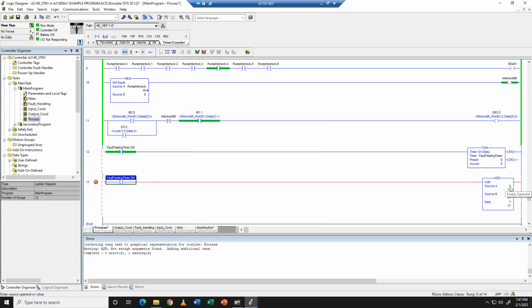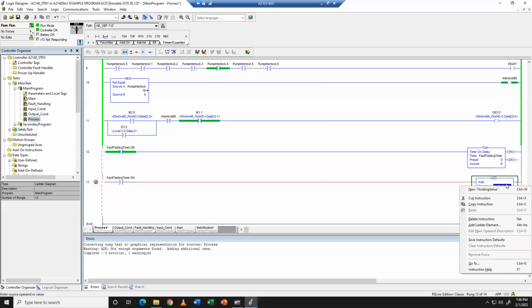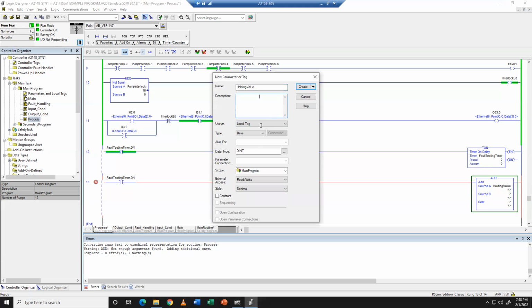So Wonderware, for example, I believe the character limit for tags is 35 characters, which seems crazy. But if you go crazy with 5 character tag fragments for pump, fault, something, with underscores to separate everything, you can hit those values pretty quick.